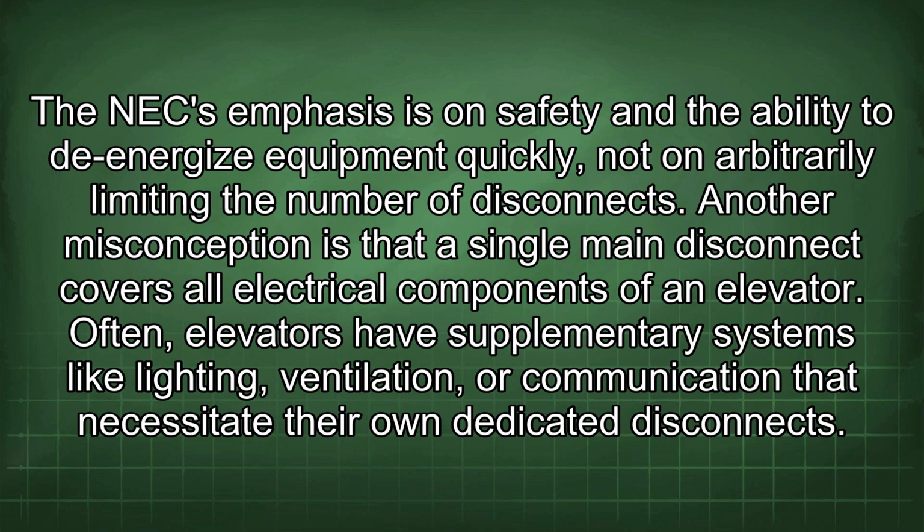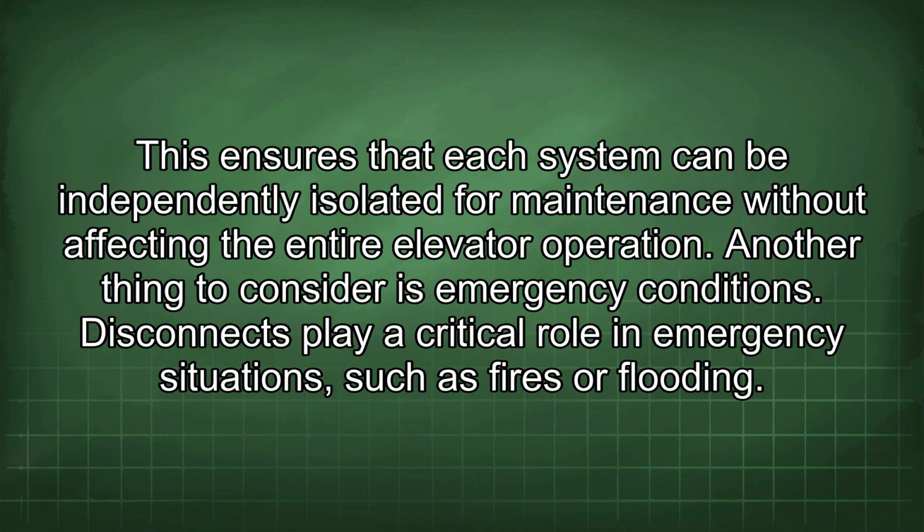The NEC emphasis is on safety and the ability to de-energize equipment quickly, not on arbitrarily limiting the number of disconnects. Another misconception is that a single main disconnect covers all electrical components of an elevator. Often, elevators have supplementary systems like lighting, ventilation, or communication that necessitate their own dedicated disconnects. This ensures that each system can be independently isolated for maintenance without affecting the entire elevator operation.